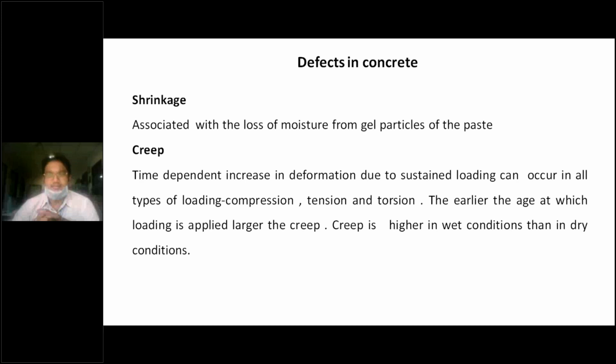The earlier the age at which loading is applied, the larger the creep, and the creep is higher in wet conditions than in dry conditions, because in wet conditions there is a possibility of more deformation in the member due to its constant loading. So in that way, these two effects are very important. We have to consider these as the major parameters. That's the reason why we use high grade concretes to avoid shrinkage and creep in the concrete, particularly in this prestressing technology.